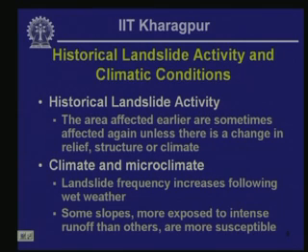So, you have to look at both climate and microclimate of the area, and the key considerations are as follows. Landslide frequency increases following wet weather, which we have already seen, and we have also looked at the reasons why. And some slopes are more exposed to intense runoff than others, and these slopes could be more susceptible to landslide.